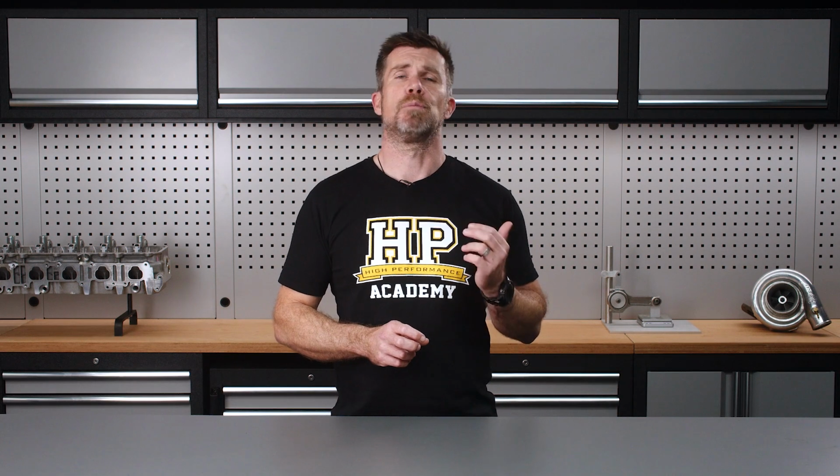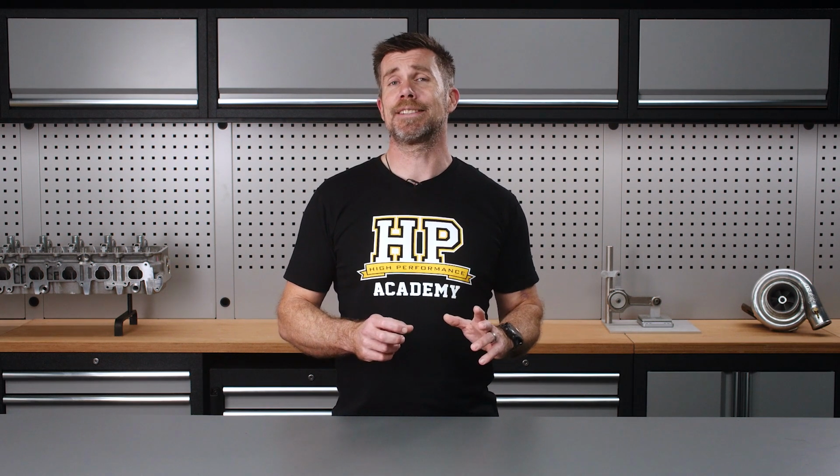In order to understand what we're doing by tuning the ignition timing, we need to understand what's going on inside the combustion chamber during the combustion event. Most people assume that when the spark event occurs, an explosion takes place inside the combustion chamber. This actually isn't the case, and under normal combustion, we get a relatively slow combustion process taking place.